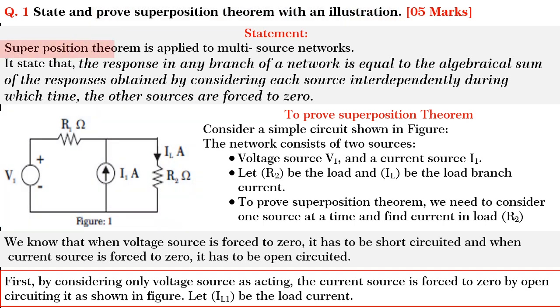Friends, we know that the superposition theorem is applied to a multi-source network. It states that the response in any branch of a network is equal to the algebraic sum of the responses obtained by considering each source independently, during which time the other sources are forced to zero.